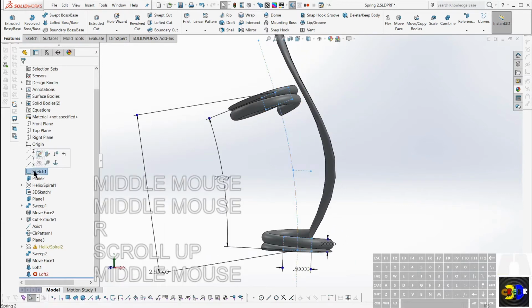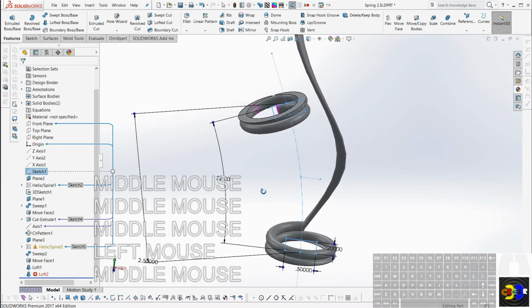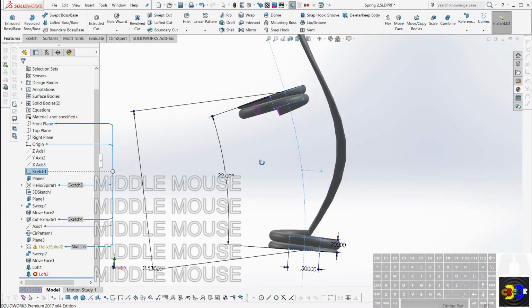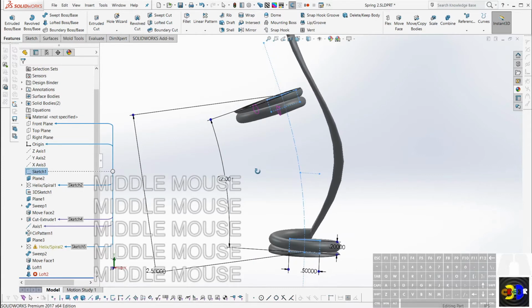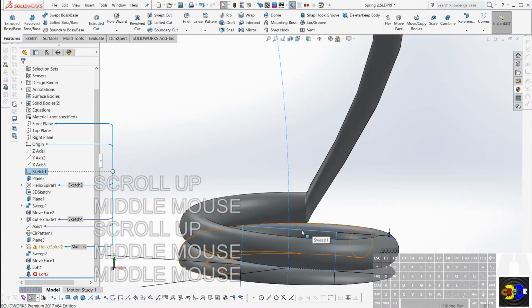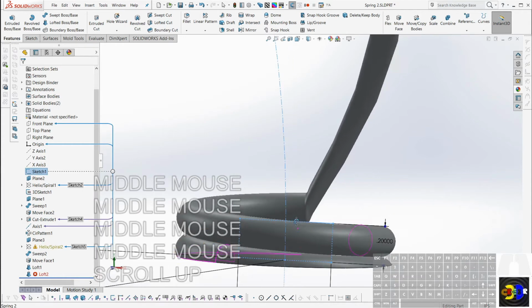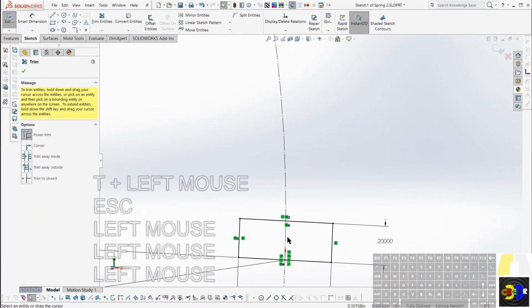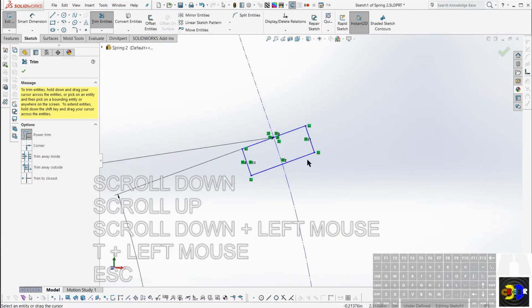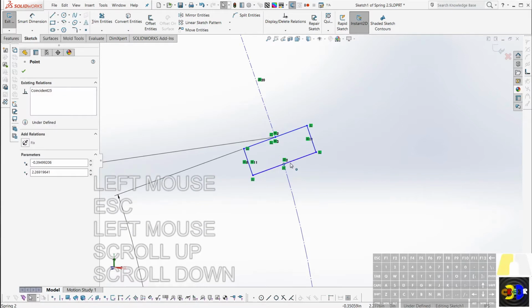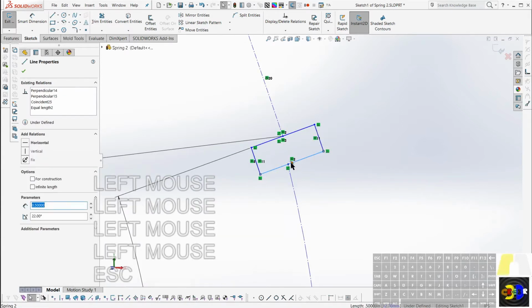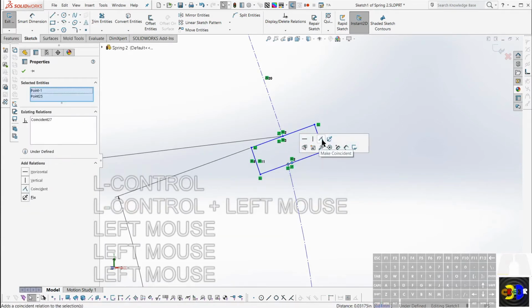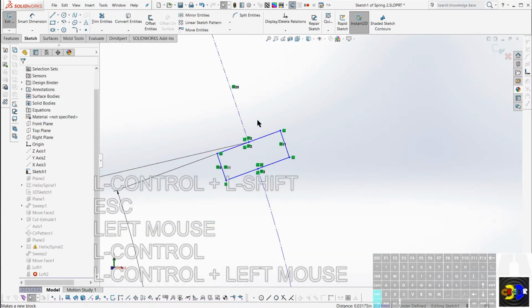Does it match our sketch? Not quite. And that is because my arc should be basically from the center point of this part of the circle, which should be coincident with this here. So I need to correct that. I messed up my sketch. So let's just trim that. Trim that. Select this midpoint. Like so.